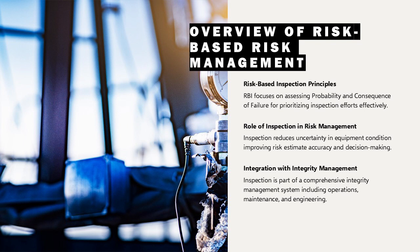Rather than relying on fixed inspection intervals or purely prescriptive rules, RBI-based risk management prioritizes resources toward equipment that presents the highest risk to people, the environment, and business continuity. Inspection plays a critical role by reducing uncertainty in equipment condition, which directly improves the accuracy of risk estimates. However, inspection alone does not prevent failures. It enables informed decision-making so that appropriate mitigation actions can be planned and executed.